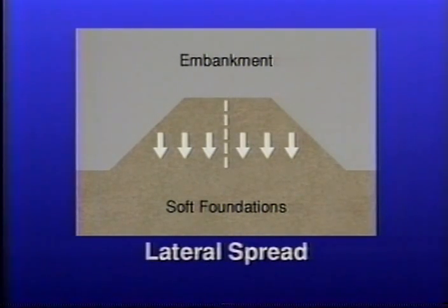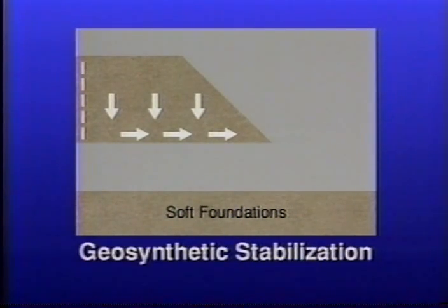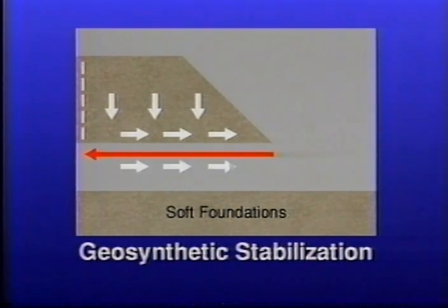Embankments, dikes, or levees constructed over silts, clay, or peat layers tend to spread laterally because of vertical earth pressures acting on the base. Geosynthetic reinforcements used to increase stability are usually placed with the strong direction perpendicular to the center line. A geotextile or geogrid resists lateral displacement.